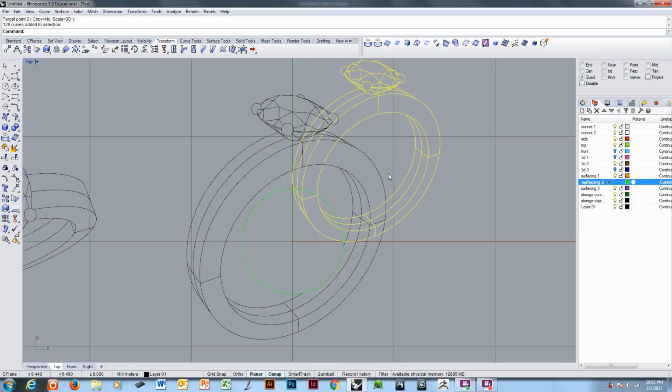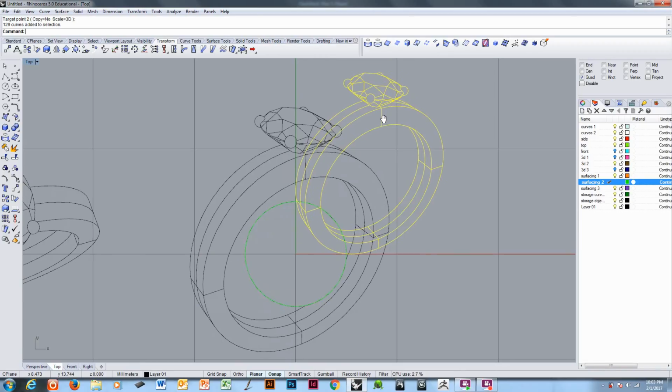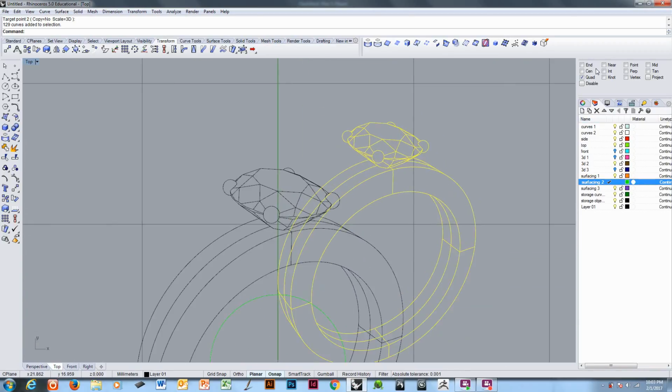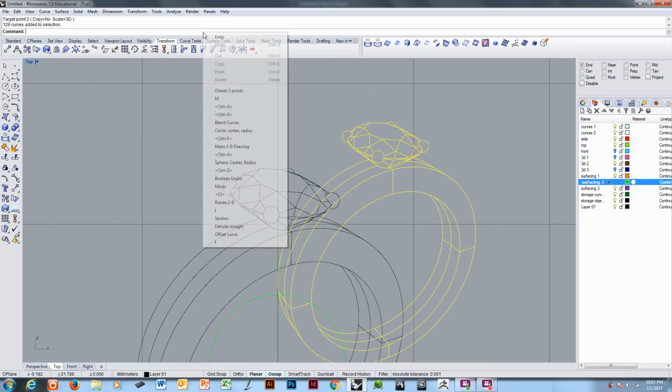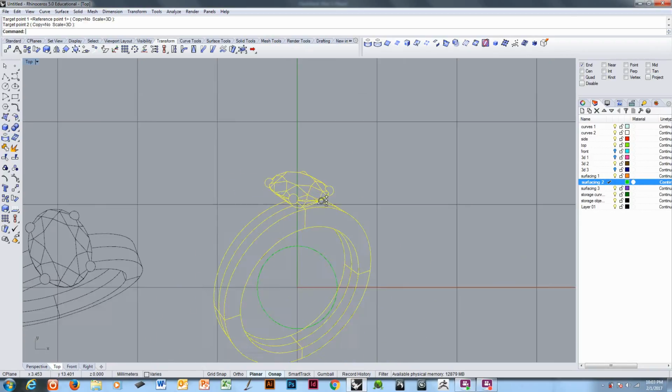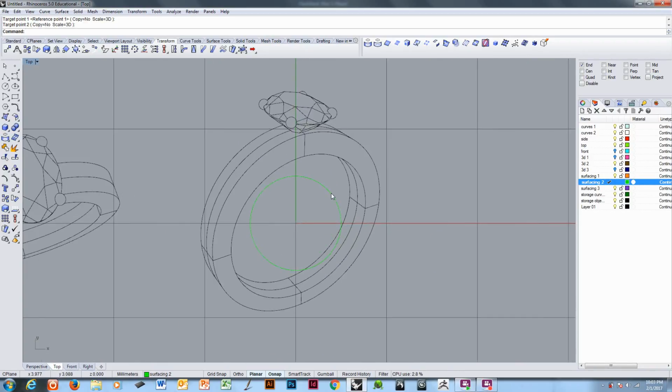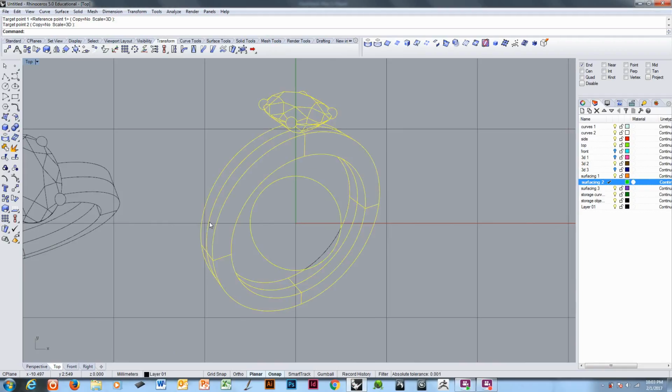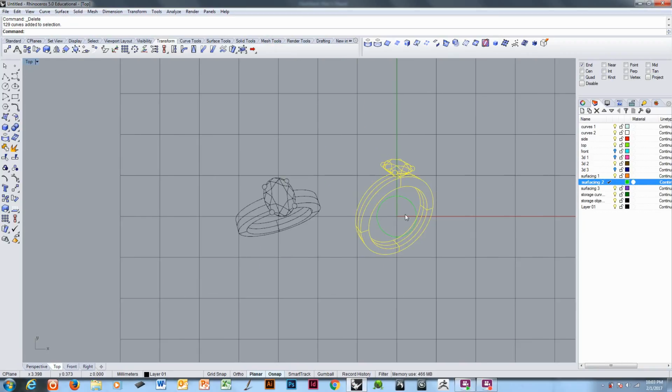This drawing, all I need is 2 lines or intersections that I can grab. This time I think I'll use a facet. So orient 2 points. This facet line, beginning and end. The same facet line, beginning and end. That's now actual size. Select the 3D drawing, the 3/4 view drawing with the sphere. Delete it and keep this one that does not.